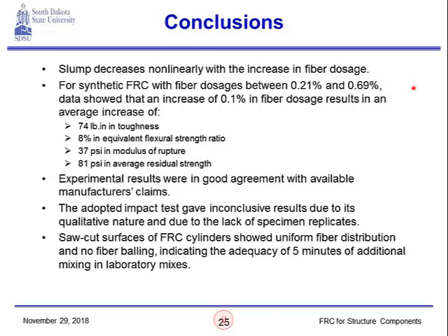proportions, basically. Experimental results were in good agreement with available manufacturers' claims. The adopted impact test gave inconclusive results due to its qualitative nature and due to the lack of specimen replicas, as I said. The cut surfaces of FRC cylinders showed uniform fiber distribution and no fiber balling, which indicates that the 5 minutes of additional mixing that we had on our laboratory mixes were adequate.